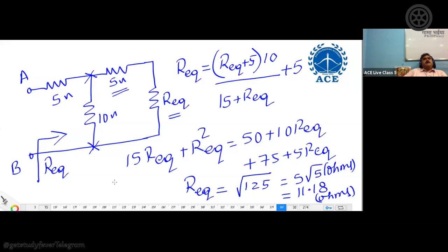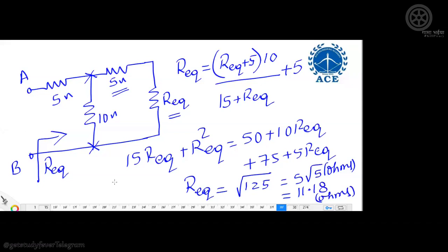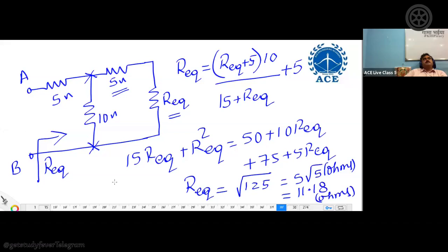At that point of time, the current has to be 63% of the final value. So what is the final value in the I1 of t expression you got? You substitute t equal to infinity. What is the final value, 0.5, right? Yes, sir. So that is the reason what I am doing is 63% of 1 by 2, meaning 0.63 by 2. That's all. Got it? Yes, sir.